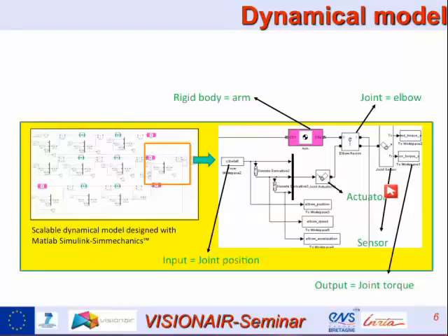Then, upon this model, we can build, so it's not so clear here, but we have the zoom on the right, a dynamical model. Here you have the joint position, you have the derivative of order 2, so you can get position, speed, acceleration, and here go through the joint and compute the torques, and so torque and forces at the joint. So it's a classical dynamical model.